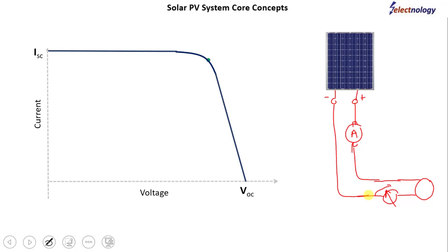At the same time we are also measuring through a voltmeter the voltage across the terminals of the PV module. Let's connect over here and over this. Now we have a voltmeter and an ampere meter, and we are measuring the voltage and ampere. And what we will do is start rotating this knob towards the right side so that we can start supplying power to the bulb.